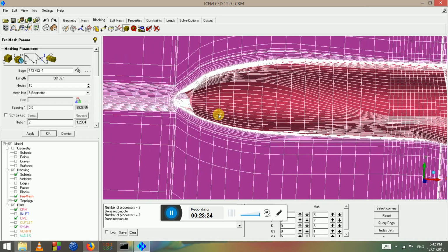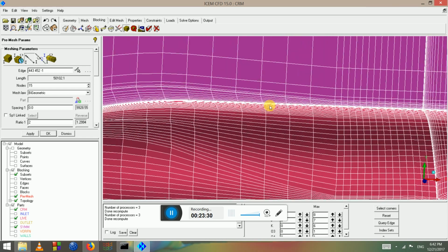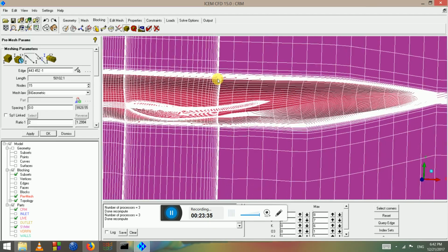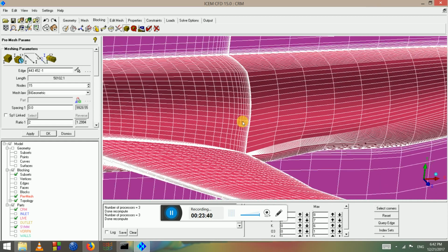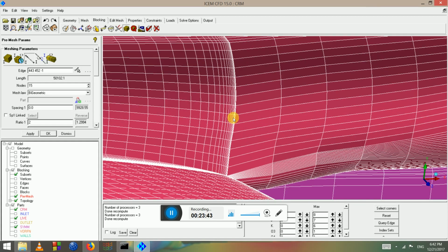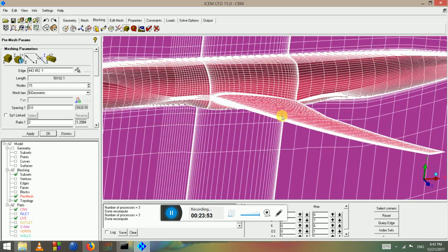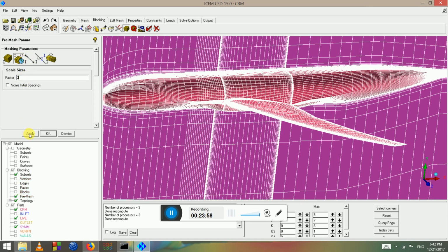Like I said, we can improve the mesh parameters for the boundary and move the edges to the right places. But this is the general idea of how to use blocked meshing parameters, and we don't recommend these. For example, the cell spacing here is really small, and the cell spacing here is really big, so that's not recommended. We can use smaller spacings, so play around with the mesh spacing parameters to improve the overall mesh quality. But let's just redo the pre-mesh and have a look.